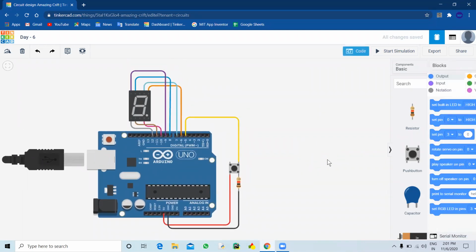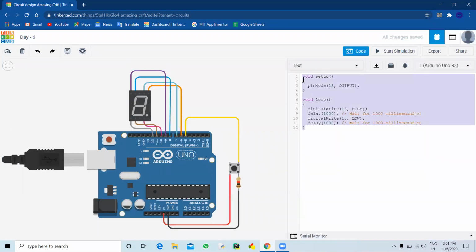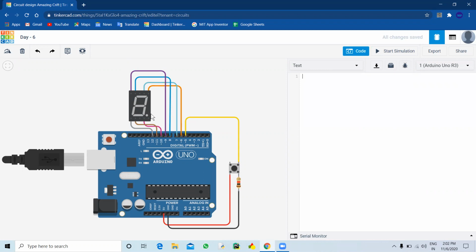Now let's come to the coding part. You don't have to define the LEDs always, like in this, you need to define it again and again. Instead of that, you can go to void setup, and in pinMode, like we give the name of the variable, you can give the pin number like 6, and then it is output, so I will write OUTPUT like this.